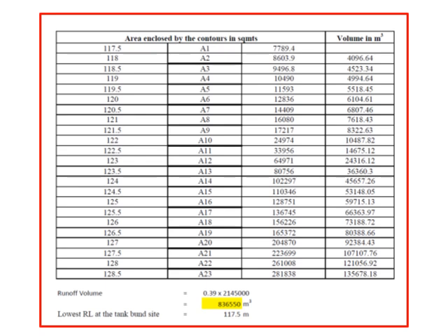Now from the previous calculation we know that the runoff depth is 39 centimeters, which comes to 0.39 meters, and we know the catchment area. This catchment area is not the sum total of these areas. It is the area that has been got from the topo sheet. You have to mark the ridge line on a topo sheet and then determine the area using the planimeter. This is the area that we measured using the planimeter, particularly from the topo sheet. So taking the catchment area and multiplying by the runoff depth, we get the runoff volume.